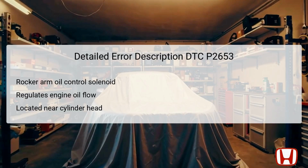The P2653 code specifically highlights an issue within the rocker arm oil control solenoid circuit, where a low voltage condition is detected. The rocker arm oil control solenoid aids in the vehicle's variable valve timing, which is crucial for improving the efficiency and responsiveness of the engine. It is typically positioned near the cylinder head, which is integral to the engine's operational dynamics.